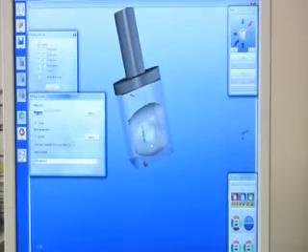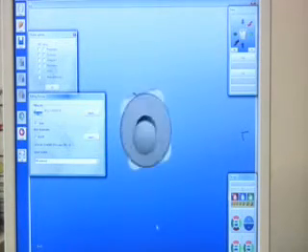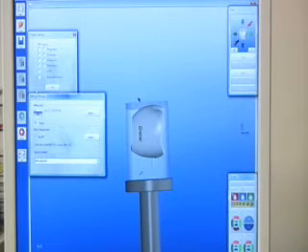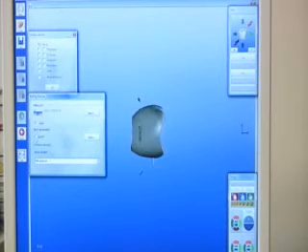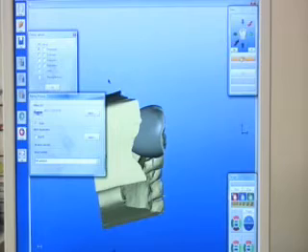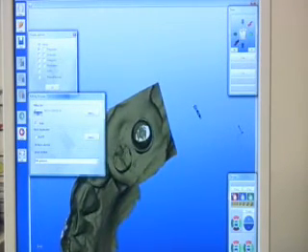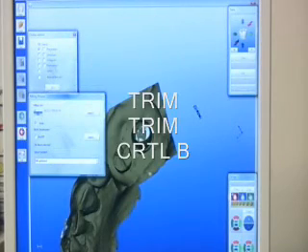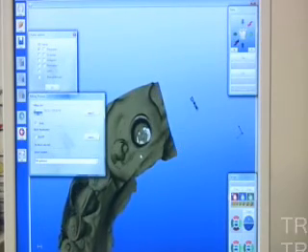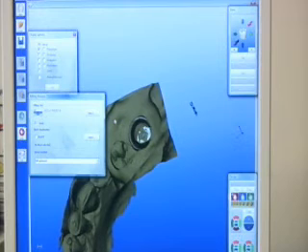I like to check to make sure that my restoration fits in the block. In some implant cases, you're going to get a message saying restoration will not fit in the block, in which case you can use your position tools to make sure your margin mills out okay. Your occlusal might be a little short. You can build that up with add-on porcelain. I also like to check the fit of it with the virtual fit checker. In mill preview, hit trim, Control B, and you can see areas of binding.